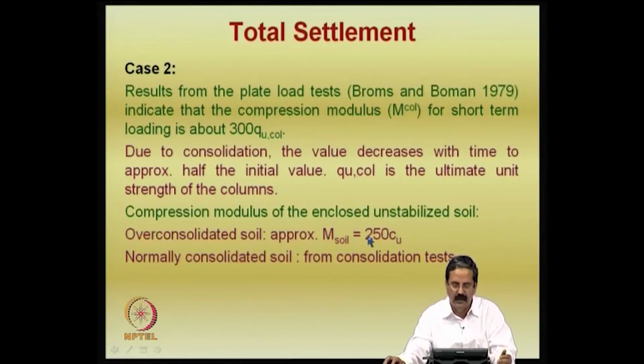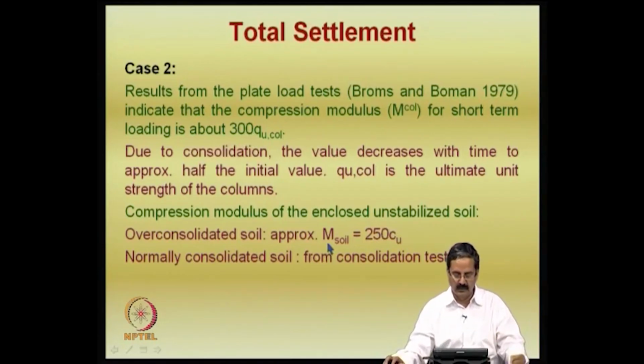That is what people have been doing, like even we did in our laboratory some of these experiments where you have a consolidated sample and, say, from 100 kPa to 200 kPa there is some compression going on, and that compression can be converted to strain. The total stress divided by the total strain gives you a modulus, right.